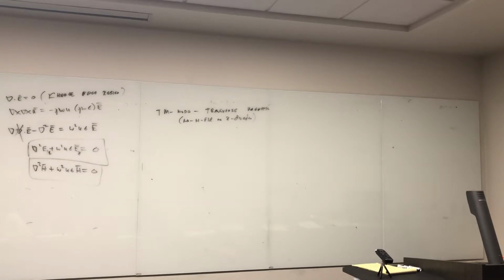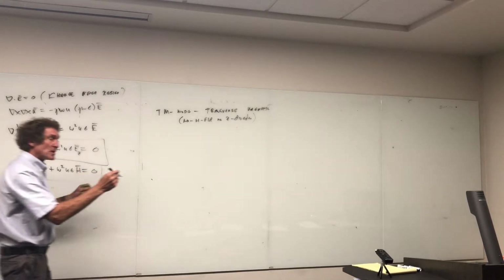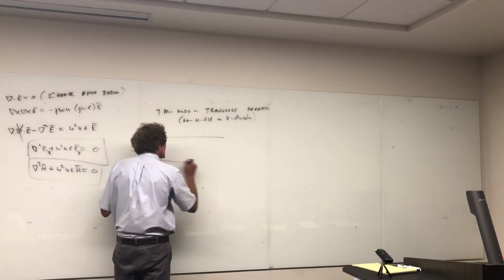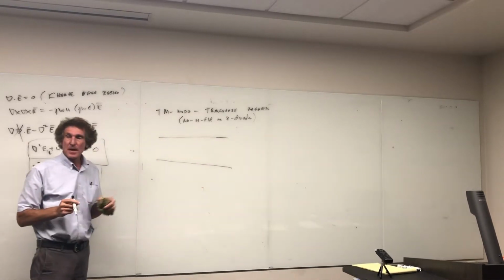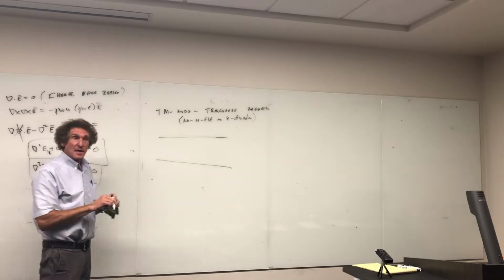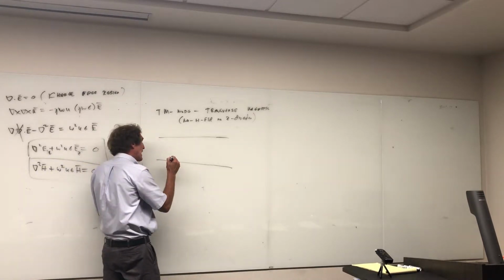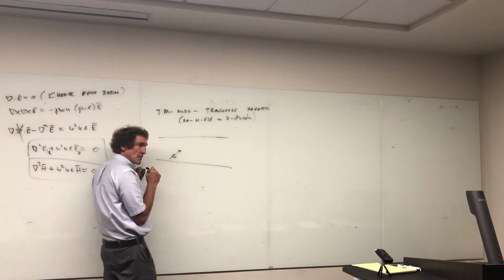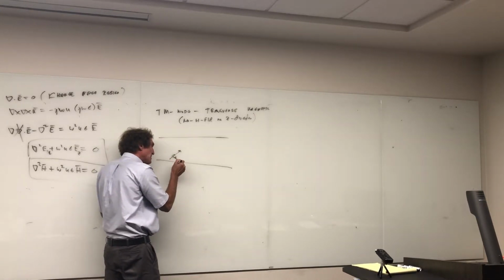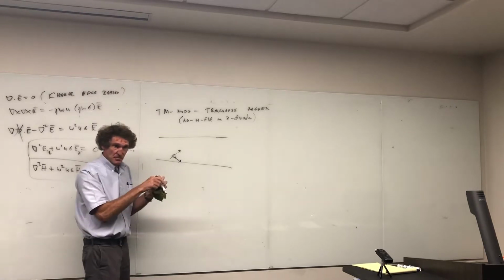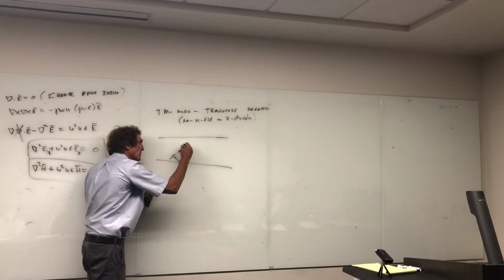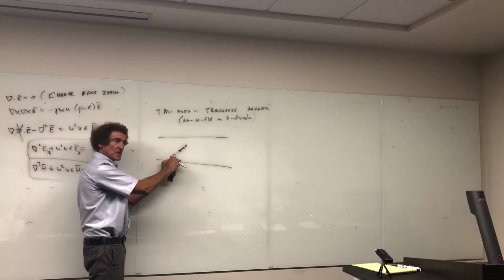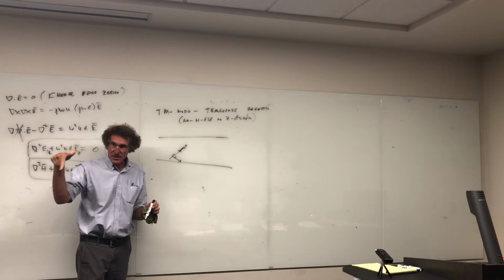This becomes very important. Now, when you look at this thing, the waveguide, I'm going to put it here, the cross section of it. I want you to pay attention to one thing. Remember, this wave is ricocheting back and forth, isn't it? Now think about this. If you have an electric field coming out, there is a magnetic field in this direction. Is there not? E cross H would be the direction of propagation. Can you all see it? If that's the direction of propagation, the wave is moving this way, and I got an E field out, and H field would be in this direction, because E cross H is the direction of propagation.